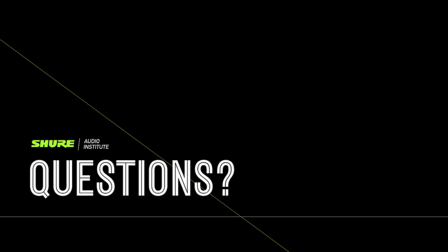The turn off time, or what we call the hold time, can be adjusted. There's 2 different values there that you can choose for how long the mic stays on once it thinks the person has stopped talking. But the activation time is within 4/100ths of a second. It's very, very fast because again, the whole idea was you don't want to clip off words or anything like that. So with an SCM810, it barely misses anything ever. It never does. Most people are never aware that they're even hearing an automatic mixer when we're using the SCM810. So hopefully that answered that question.